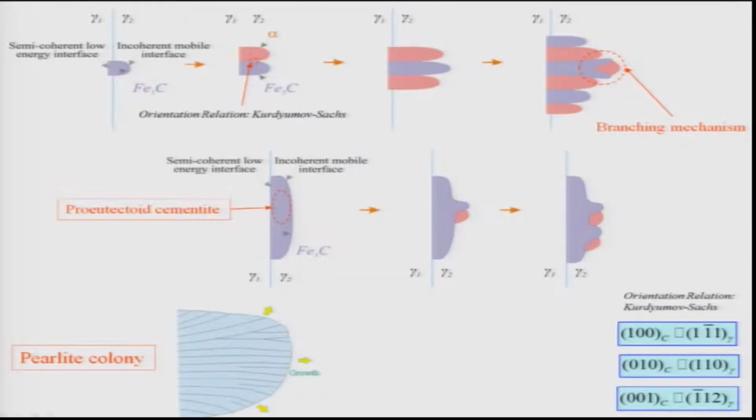So, what will happen is, as Fe3C is a carbon-rich compound, it requires more carbon for its growth. When it grows into one of the grains, it has an incoherent interface with that grain. That is obvious, because the grain with which it has a coherent interface will remain stagnant, because it will like to keep these coherent or semi-coherent interfaces present. It will not try to disturb them. That allows it to have low energy, and the grain with the incoherent interface will be the one which is mobile.